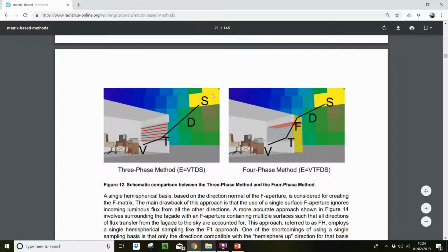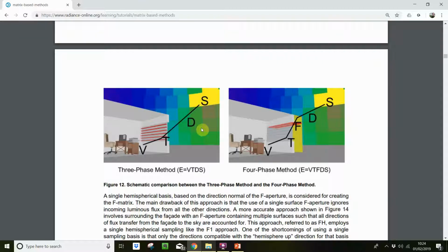From the outside you're doing like 2 ambient bounces, and you've got your ambient accuracy set reasonably low, because the most important part is understanding obstructions, but there will be reflected light as well off the ground, off surrounding buildings. But because of the size, you want to keep that calc lightweight.